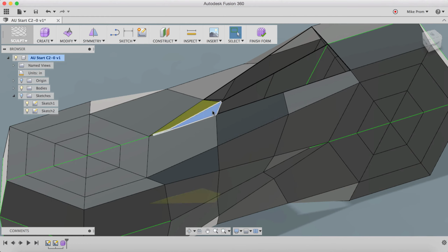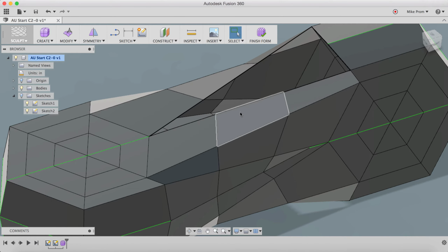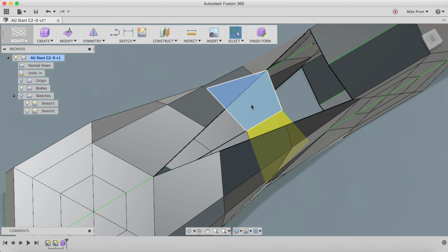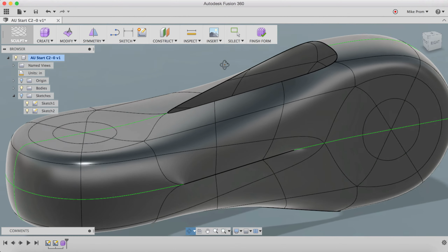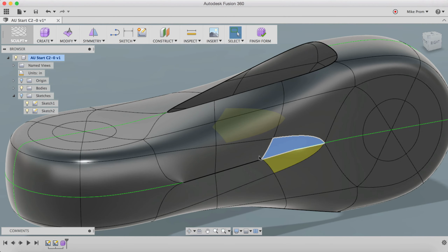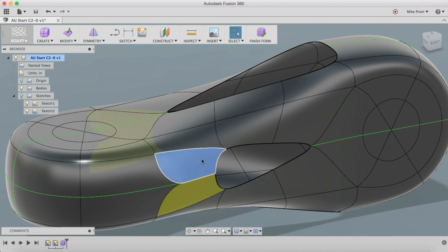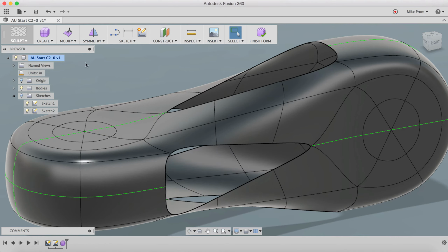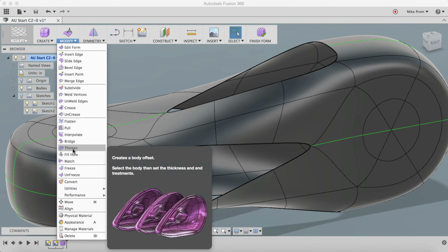Because there are segments in the middle now, it goes into box mode. By simply deleting the segments in the middle and rotating, you can see from the top there's more. By the time I delete the last one, it will go back into smooth. Since I want this symmetric, I'll delete the same faces on the top and the sides. I'm left with 4 holes, and I can use my fill tool to fill in those holes.